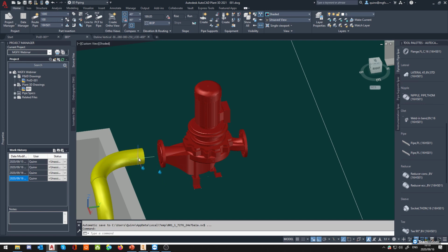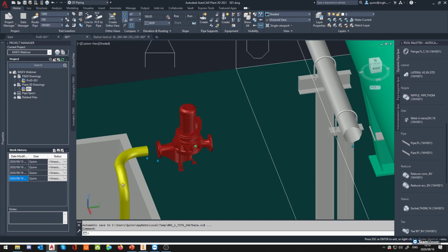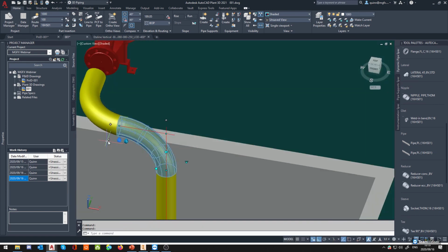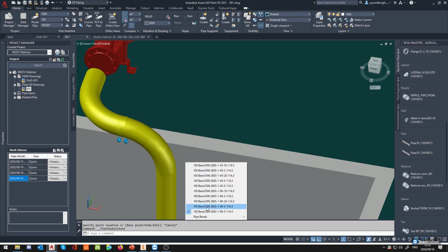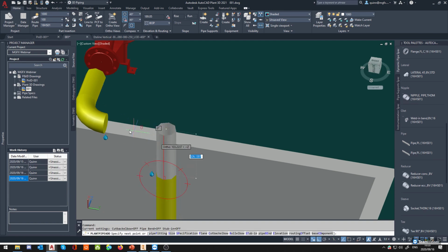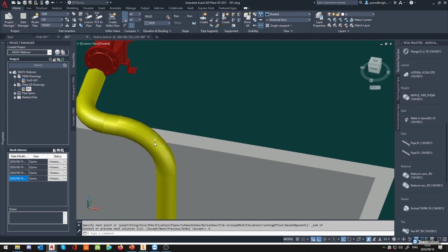Sorry, Jacques, I see that you said something about the bends overlap. Were you meaning about the bends over here? Ah, yes, those. The reason why it overlaps is because I've got long radius set as default. So to fix that, I can just change this to short radius. That would actually be taken care of in my spec editor. So, yeah. What I could do is just put it back and then we'll snap it there.